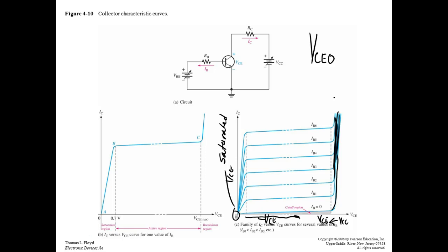And something else in your circuit might be destroyed. Because if the transistor shorts, that's what usually happens. When these solid state devices short, it usually cascades, which means this guy will short and pop something else, and it'll burn resistors up, right? That resistor was designed not to handle a short circuit. So you short the transistor, and you've got that collector resistor up there, 1/8 watt, 1/4 watt, and all of a sudden it's doing 5 watts. It's going to burn up, which could cause all kinds of things to happen. So this is the problem we have with solid state. When one thing fails, it usually causes multiple things to fail.